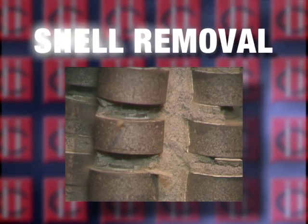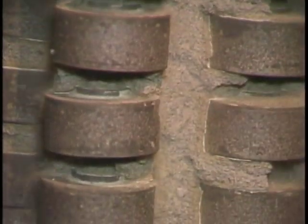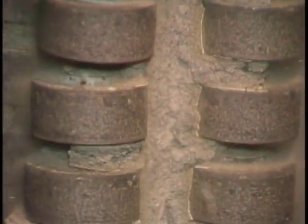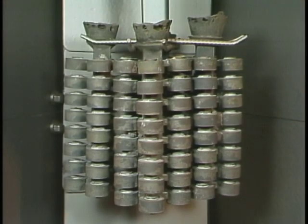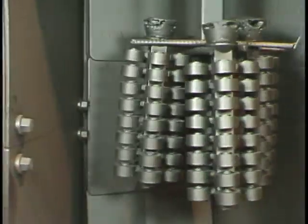The last stage of the process is to remove the shell from the newly formed casting. After the molten metal is cooled, the ceramic shell is removed either by vibratory methods or with high-pressure water jets. In some cases, the remaining shell material is removed in a blasting cabinet, with the resulting casting assembly looking exactly like the wax assembly previously seen.